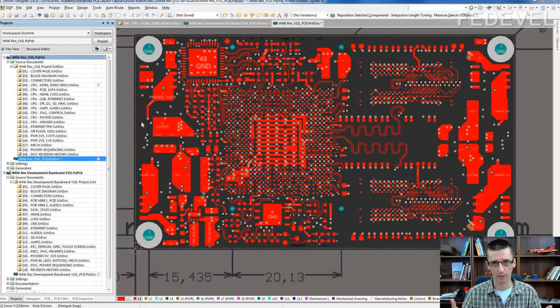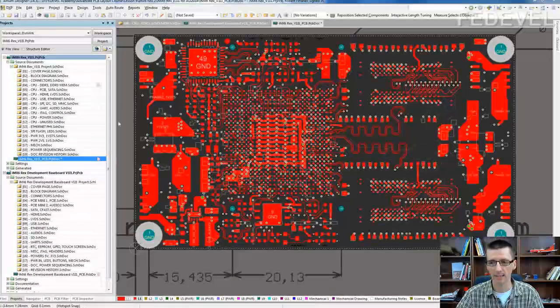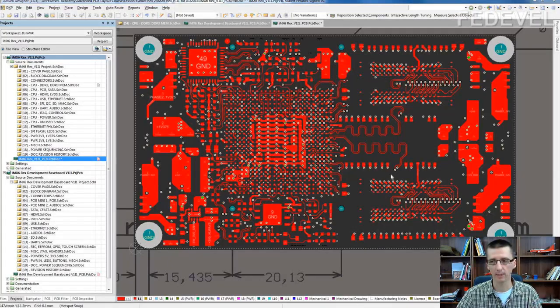If they are not connected properly, they can make the EMC results of your PCB worse. So normally in my designs, I use the second layer from the top and second layer from the bottom as solid ground planes, and I do not place any big ground planes on the top and bottom layer. No problems.